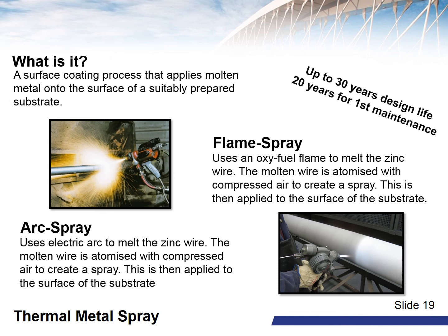The life expectancy of the zinc thermal metal spray is approximately 30 years and has been known to regularly exceed this duration. It has been known to exhibit greater than 20 years performance up to first maintenance, even in harsh marine environments. Zinc thermal metal spray can be applied up to approximately 250 microns of thickness. Providing the coating has been applied correctly and without spatter, there is no need for any fettling processes due to the smooth finish that thermal metal spray provides. As the coating is porous, a suitable sealant is recommended.